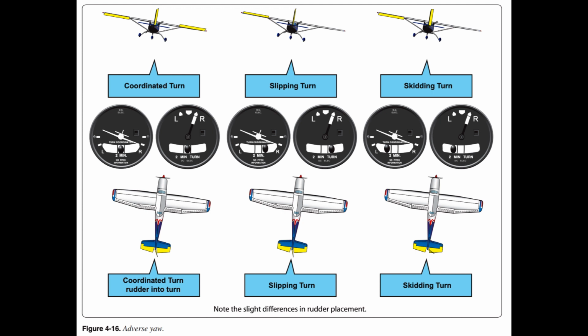Any force applied to an aircraft to deflect its flight from a straight line produces a stress on its structure. The amount of this force is termed load factor. A load factor is the ratio of the aerodynamic force on the aircraft to the gross weight of the aircraft, e.g., lift/weight. For example, a load factor of 3 means the total load on an aircraft's structure is 3 times